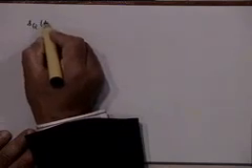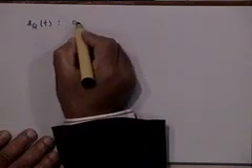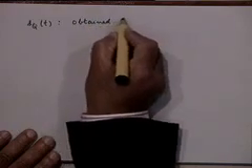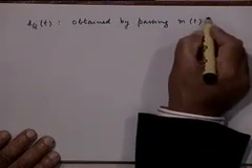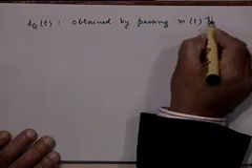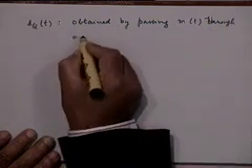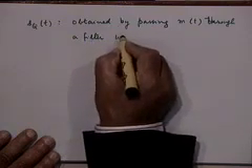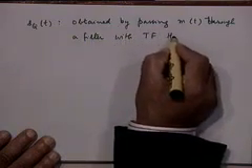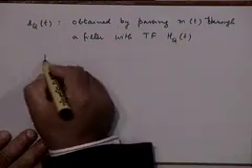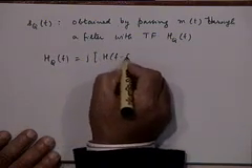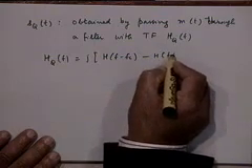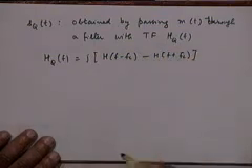So S sub QT can therefore be considered as obtained by passing the original message signal MT through a filter with transfer function, let us say H sub QF, where H sub QF is J times H of F minus FC minus H of F plus FC.